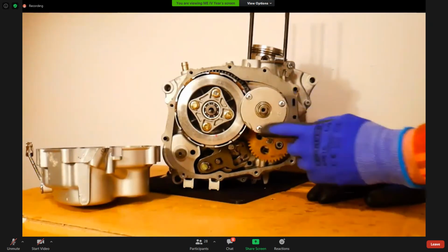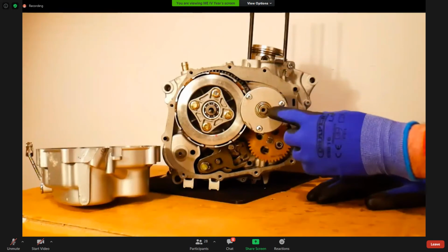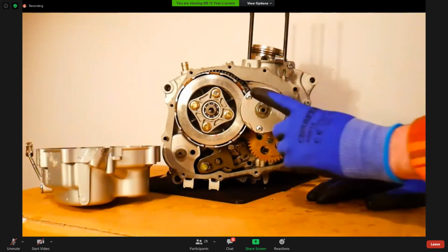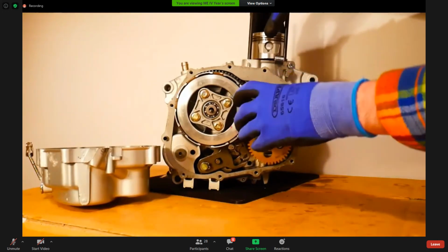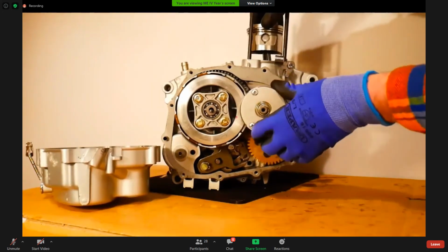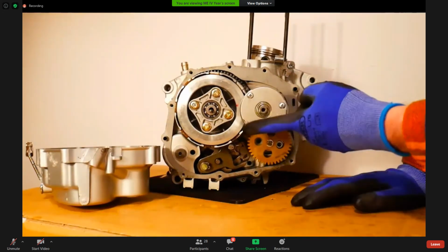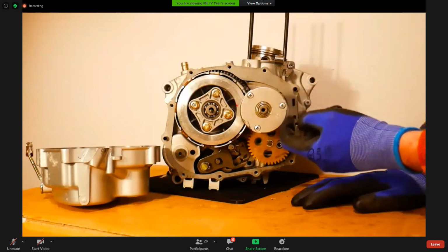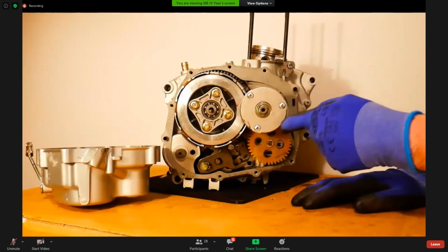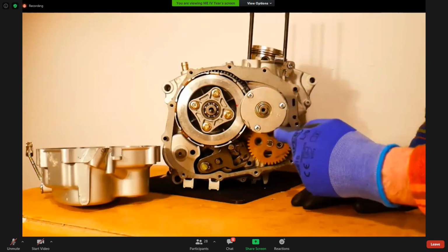It's called a centrifugal oil filter because as the oil comes in through this little valve, due to the rotation of the filter, and you have to imagine that it's rotating at very high speed, the oil gets flung to the outside of the centrifugal oil filter.